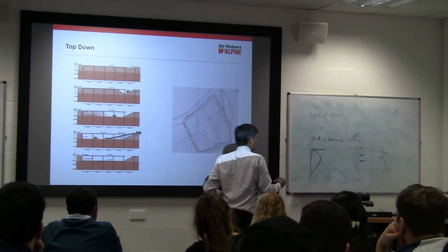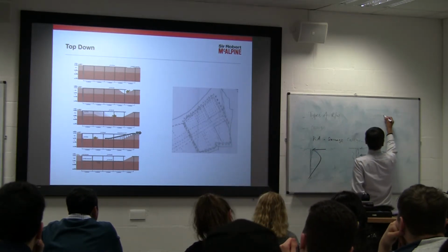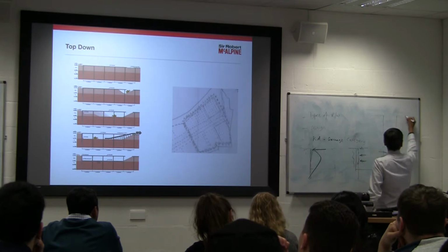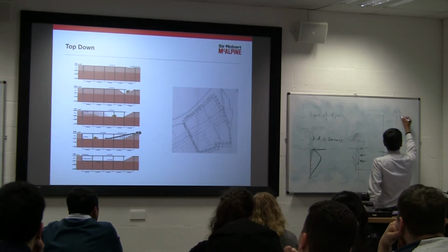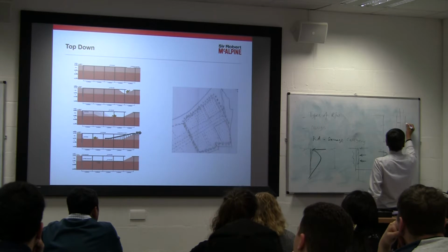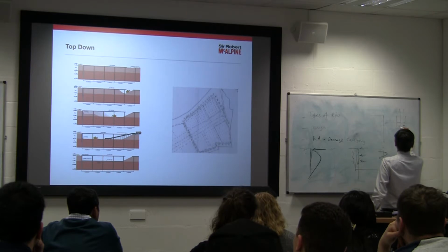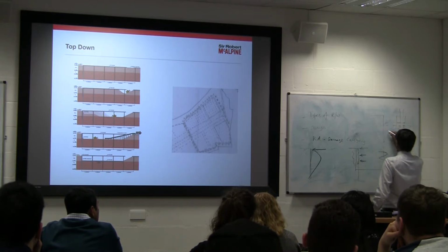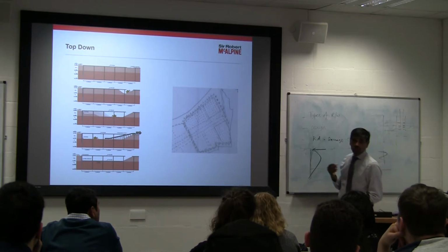So by the time you get down to expose the plunge column, you've got a casing there, the plunge column gets in there, there's a template there, there's a template there. So when you actually cut the piles, you can see the shear studs on the plunge column tie up with the floor levels within the gaugeable tolerances. That's the floor level you are going to tie up. Yeah? You see what I'm saying?